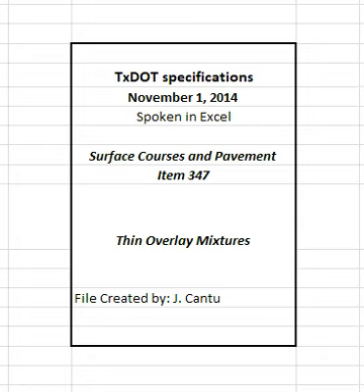Use no more than 1% hydrated lime when using crushed gravel. Do not add lime directly into the mixing drum of any plant where lime is removed through the exhaust stream unless the plant has a baghouse or dust collection system that reintroduces the lime into the drum.